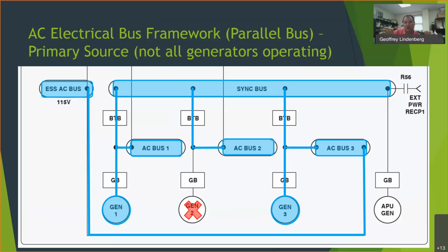Whereas if you have a split bus system, like the first example I showed, and something goes wrong on bus 2, the fact that they're isolated and those contactors in the more modern aircraft, there are computers monitoring all this stuff, they would see that problem before they switched over the transfer switches. And so you don't have as big of a risk of a failure on one bus taking out equipment on every other bus. This can go a step further here.